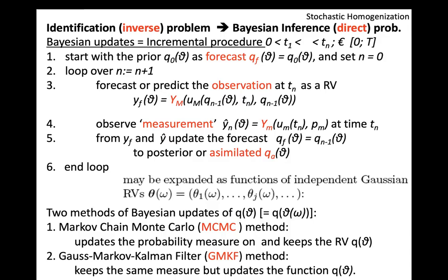So it's always a good idea, like when I showed you roughly how we try to identify the damage model parameters. If you can split it into blocks of these parameters, initially you consider some of them deterministic, and you take the measurements which are only pertinent to those that you try to identify, and so on and so forth. So they kind of reduce the size of your problem in terms of identification. This is always a good strategy. And only at the end, you try to build all of them at once to see if you are really fitting correctly.